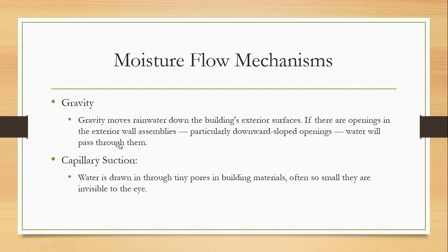Then you also have capillary suction. So another mechanism. Water is drawn in through tiny pores in the building materials, often so small they are invisible to the human eye. So I gave you an example before, for example, where you have moisture in your wall that rises up the wall.